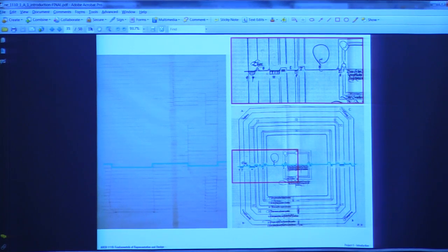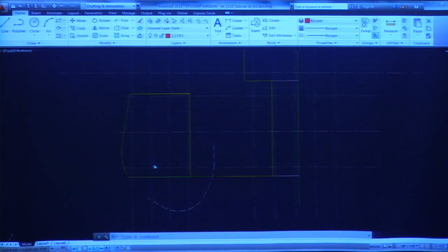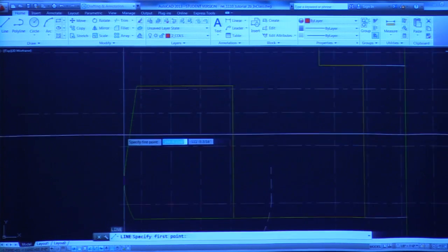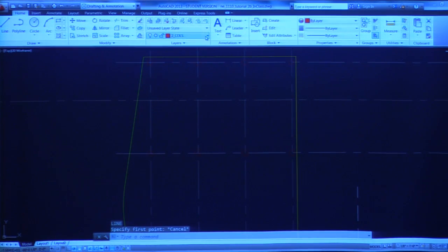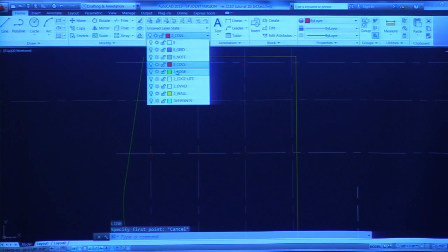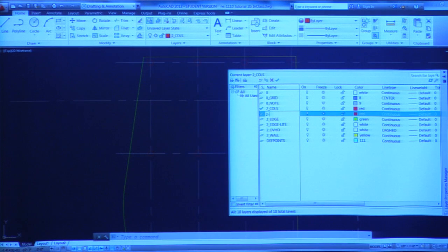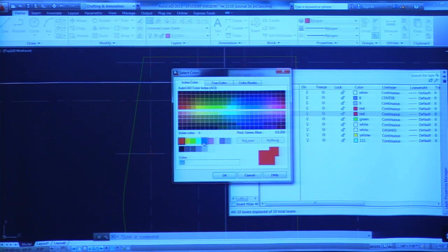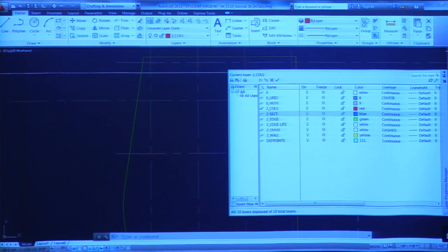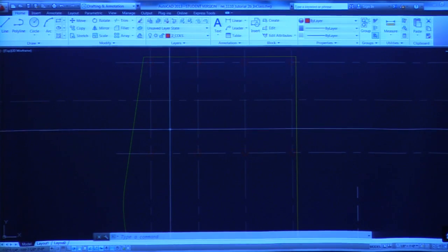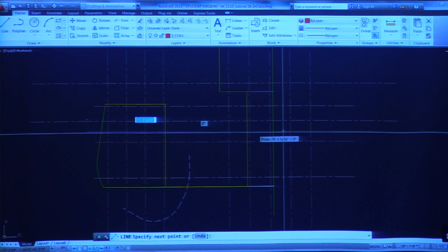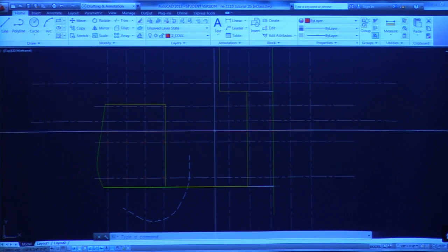This is actually an example of that for the hand drawing. My take on it is that I'm going to drop down to a layer that I don't have here. So I'm going to make a new layer called 2, because it's 2D, 2 dash, what did I call it? Section? SECT, caps lock. It's continuous. I'm going to call it blue. OK. Close that out. So I'm going to first just draw my section line across here. Whoops, wrong layer.